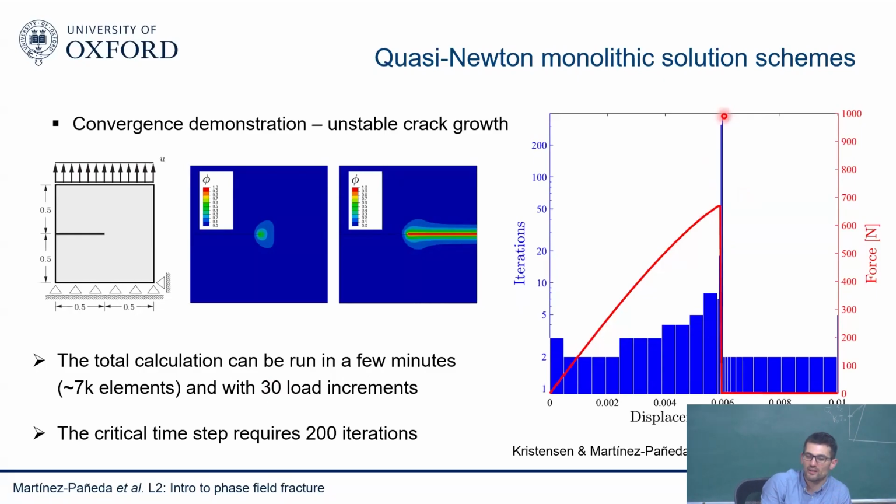Because normally, and in fact you need to tell Abaqus, with Newton methods, if you don't get convergence in 5 or 10 iterations, then you lose all hope. Newton-Raphson is not going to find the solution. So normally Abaqus will stop looking for solutions at 5. It will just start decreasing the load increment and doing other things. So you need to tell Abaqus, give it a bit more time, because it may find the solution.